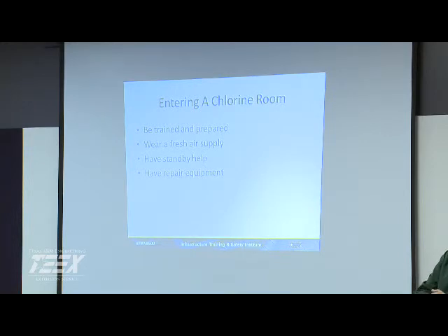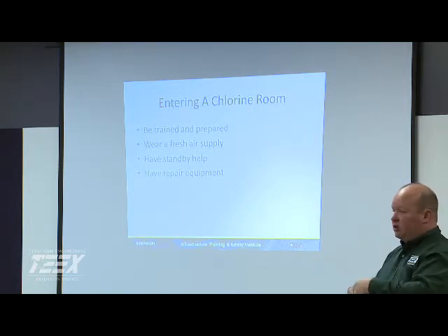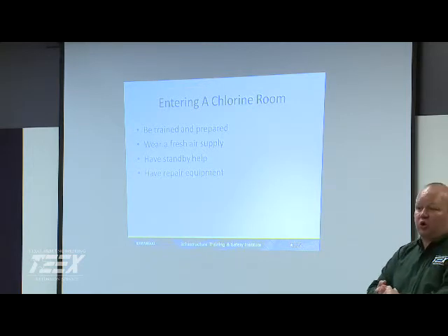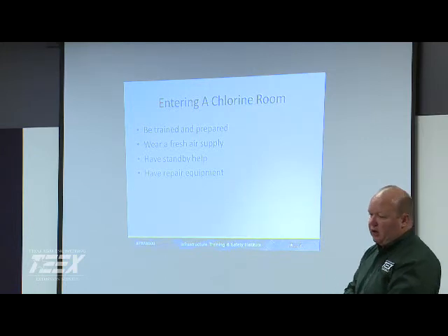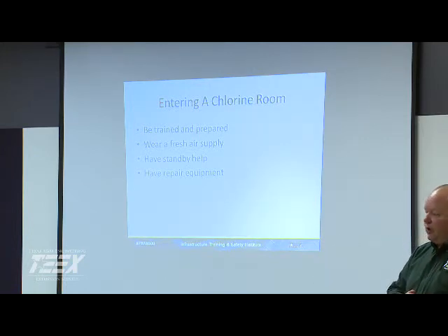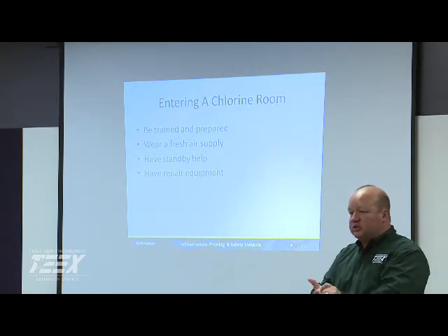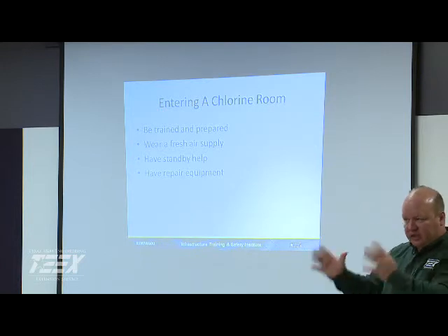One of the things I would do is look at who would be your responders, and it's not the volunteer guys, it's whoever they're coming with, from the hazmat group. Have them come in, use an empty cylinder that you've kept around. Sometimes you can buy cylinders that are set up to work on simulated leaks, which are very beneficial and not a whole lot of money. And you can simulate a couple of different types of leaks. Have it in a program where somebody opens up the kit once a month, once a quarter, something like that, pulls everything out, does an inventory, has it sealed. Make sure that they're not borrowing tools out of it. It's gotta be dedicated.